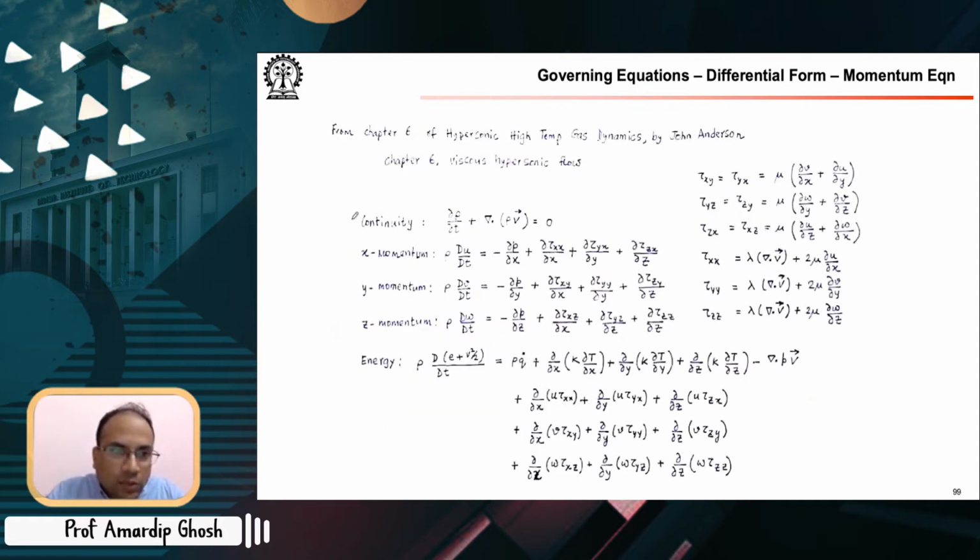We said that we have the continuity equation, and we have the x, y and z momentum equations. We will get into the energy equation in a moment, but at this point we saw that there were rho, u, v, w. So one variable, two, three, four variables. Then we had pressure, and then we had all these viscous stresses, shear stresses and normal stresses. Now the thing is, we have only 4 equations, and we have a lot more variables.